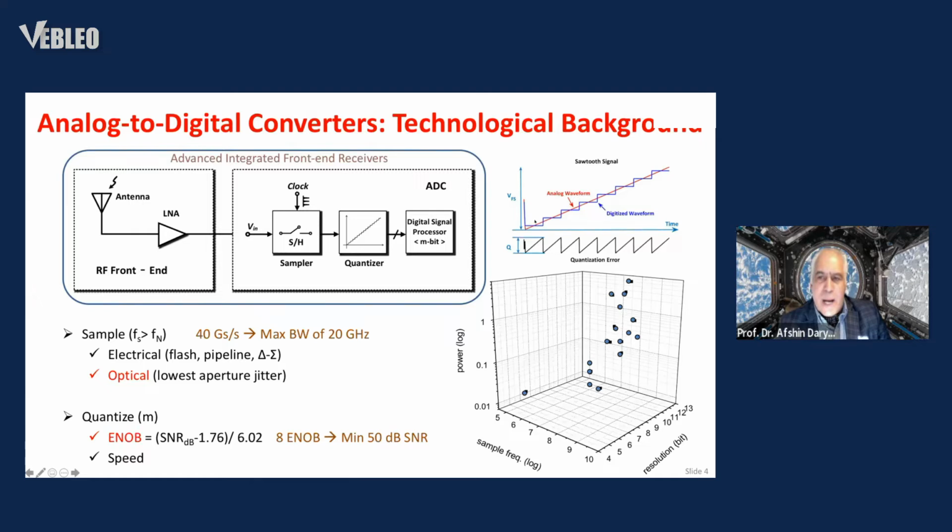If we look at a ramp signal as indicated in this graph, you can quantize it as shown here with 16 different levels. You would end up with a quantization error, which is the difference between the analog information and the digitized version of it.